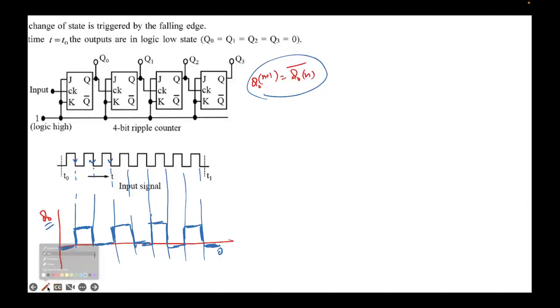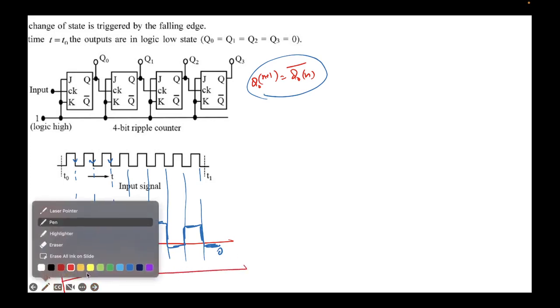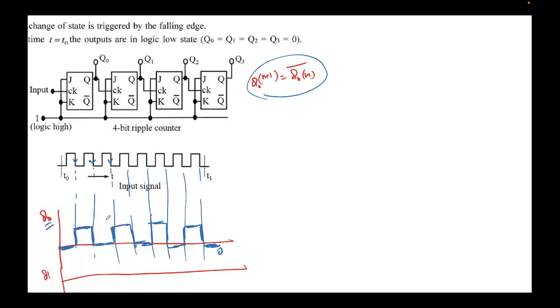So again I'll draw the value Q1. Okay, simple. Let's draw Q1 now. I'll use green color. So now look at Q1. What is Q1? Q1 is the output for this ripple counter. Let's say J1, K1, and this is Q1, right? Since this is a JK flip-flop, the truth table remains the same. J1, K1, Q1(n+1). If both are 1, Q1(n+1) will be nothing but Q1(n) toggle.